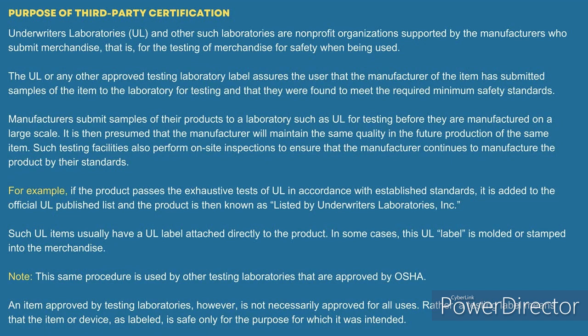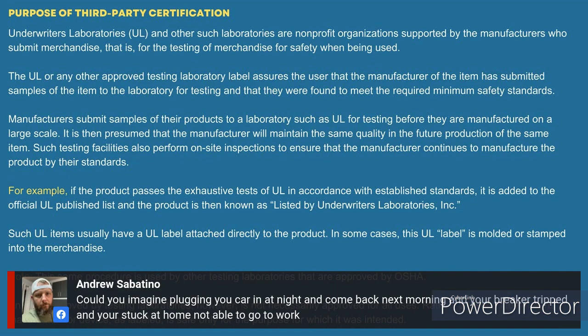They're trying to tell me that UL hadn't done the testing on that equipment for safety. Yeah, and Andrew makes a good point. This is exactly what me and James said. I couldn't imagine putting a Class A device on there when the manufacturer says a Class A device is not compatible with that equipment. So that's why they included a 20 milliamp GFCI at the unit for personnel protection.